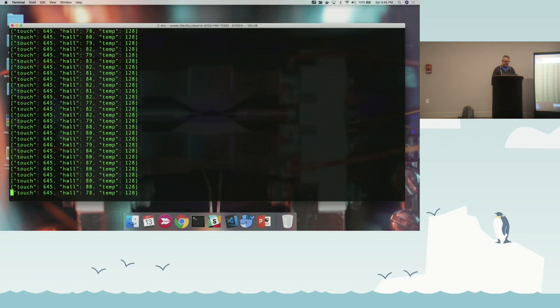So I'll try to get the temp to go up. The temp currently is saying 128. I'll put my finger on it and see if I can get it to go to 129. Sometimes I can get one, that's going down, yeah. It's a really, really bad sensor. I have held a lighter to it, and I can make that work, but I thought that probably wouldn't be appropriate. If you want to calibrate, just throw it in the refrigerator, have a little thermostat.